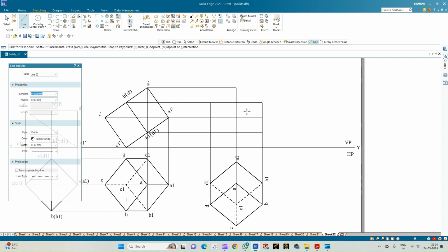So now we have got the points of intersection of the horizontal and the vertical projection lines, and now we shall complete the front view of the hexahedron. So select a line of thickness 0.50 mm. Let us begin with the corner A1. So for the observer, the corner A1 is the farthest point. So first we'll complete the hexahedron and then go for drawing the hidden edges. So let us start with the top face, which is ABCD.